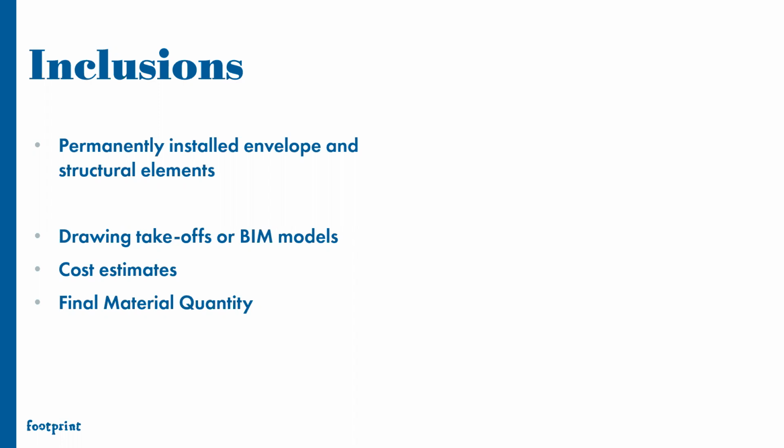This would be everything from your footings, your foundations, your slabs on grade, your walls, your roofs, your windows. These are all items that are included. And typically for these, we would go from, for example, the exterior wall all the way to the interior finish, like the drywall. But for roofs, we typically just go through the envelope into the structure, and interior finishes are something that, depending on which rating system you are looking at, or what your personal inclusion of this is, may not be included as well.